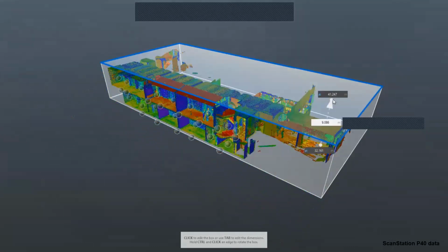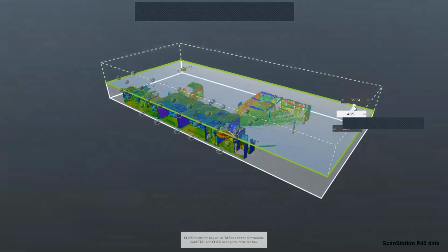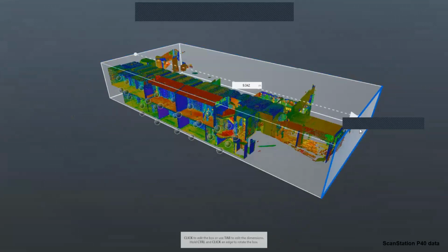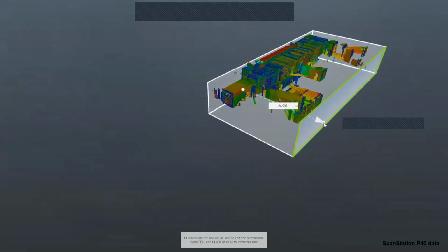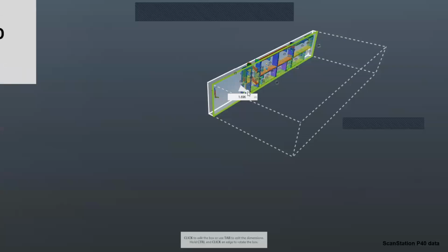So this is a BIM model, or this is a scan which is captured, and now you can go for horizontal and vertical slicing of the building to understand at what level the different solutions, different layers are, where the building is constructed accurately, what are the areas where deviations are more, and what are the areas where deviations are less. So we can actually do this comparison without even making a BIM model from the site. We can straight away compare our BIM model with the 3D scanning data.